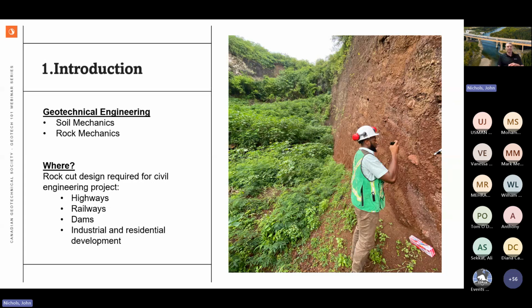So this represents a rock that can be scratched with the thumb, broken into small pieces by hand, but it has tensile strength. Just for reference, if people have done some coring and you take a typical piece of core at NQ size and you're able to break it by hand, I would say that's typically about a 12 MPa rock strength. In comparison, typical concrete is probably 20 to 50, and rock can exceed up to 400, I would say. So we're talking a very weak rock, most people might not even call it a rock.